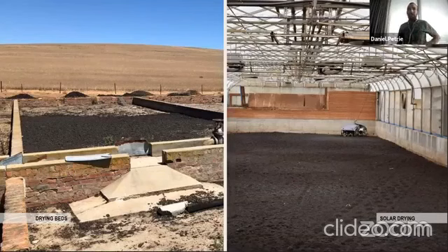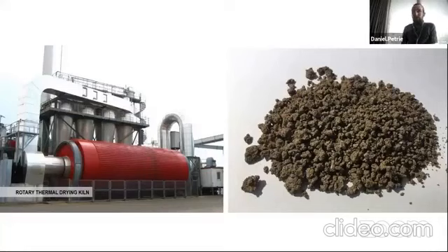If you don't have the space for that, or the interest to build a huge greenhouse and then fill it with sludge, you might consider a more compact but a more energy intensive option, which is to import heat, either gas or oil, or even if you have to use electricity, generate enough heat to pass through a kiln and dry the sludge until it's really bone dry.